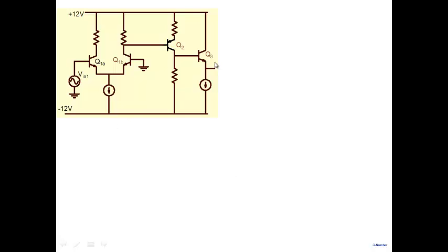The other thing was that we put a common collector stage here, and we have said many times that when you use a common collector or a common drain, the best way of biasing is through a current source. If you bias it through a resistor, the current requirement to achieve a particular swing is very large. If you bias it through a current source, the current requirements become more modest.